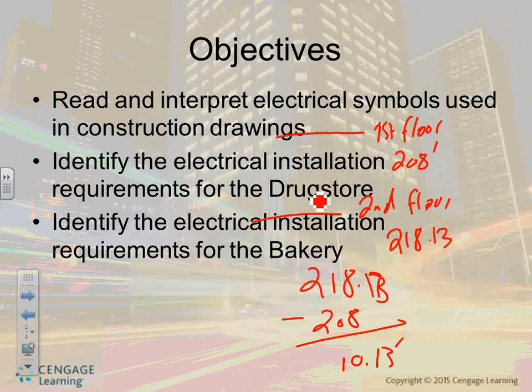So 10 feet at the top, and here's an 8.6. It looks like there's a suspended ceiling. Can you see? There's a suspended ceiling right here, and it's sitting at 8.6. Now, what would that tell you? If your ceiling is suspended at 8.6, when you mount your fixtures, gentlemen, you will mount them at what? If they're recessed, 8.6. That's what's so important, guys, in Revit. When you drop your fixtures, in Revit it's easy because they immediately host to the grid. But sometimes you put them outdoors, and you have to pay attention to the height. What's the height?